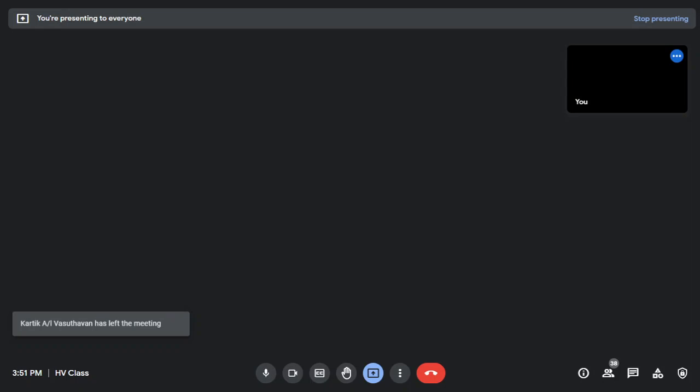Alright. Next, we are going to have the HVAC test. Okay, this is quite straightforward. You can conduct an HVAC test on any specimen that you like. In this case, we are testing the cross arm tower. We have the tower, we have the cross arm, and we have the conductor. How we simulate the real working environment is by using a spraying system.